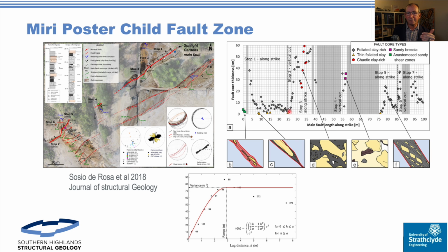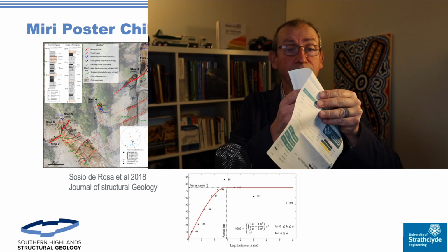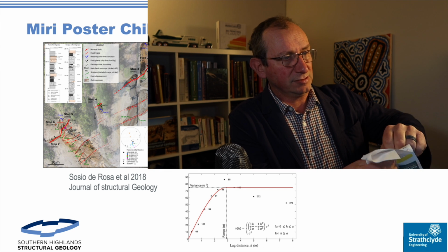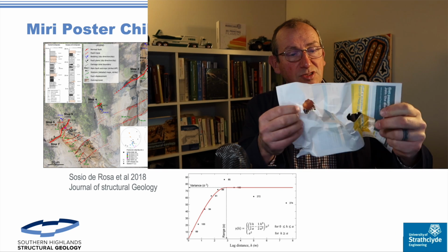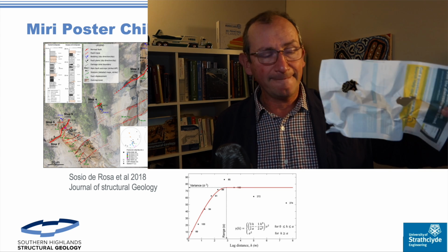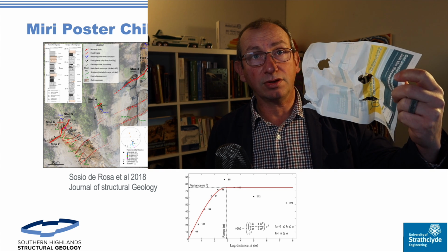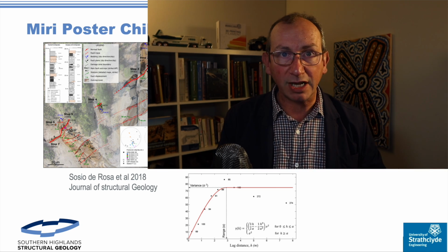So there we've got ourselves thick fault rock, but as far as the fluids are concerned, it's how thin it is, not how thick it is, that matters. So effectively what we're saying here is, here's my fault zone. This is my fault zone now, because I've got myself a set of holes all through this. And in terms of the hydraulics of this, those holes are actually more important than how thick it is, and the geometry of those holes. And we'll come to area in a little bit.